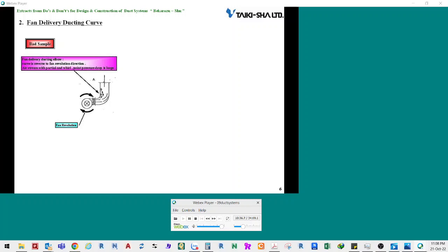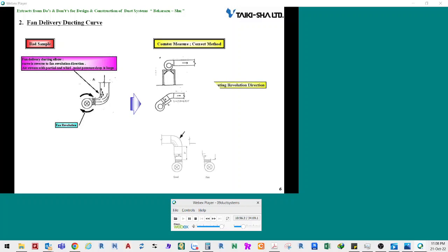If the resistance in the duct increases and the required flow rate is not given, excessive energy is used. In addition, such situations may cause fans to generate vibration and noise. In the worst case, fans may break. In such a case, take measures as shown in the drawing on the right side. Extend the cross-section area of the duct. In other words, make the wind velocity slower.